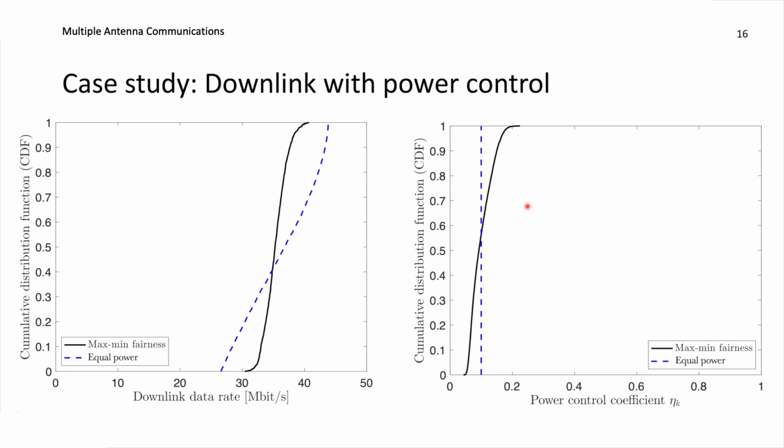Because if you have a 50 decibel difference in your beta parameter, then that means that the users that have a much better channel than you will have to cut down on the power by roughly 50 decibels in order to deliver the same received signal quality and therefore a similar amount of interference. But in the downlink, everyone is getting their desired signal and their interfering signal through the same channels.